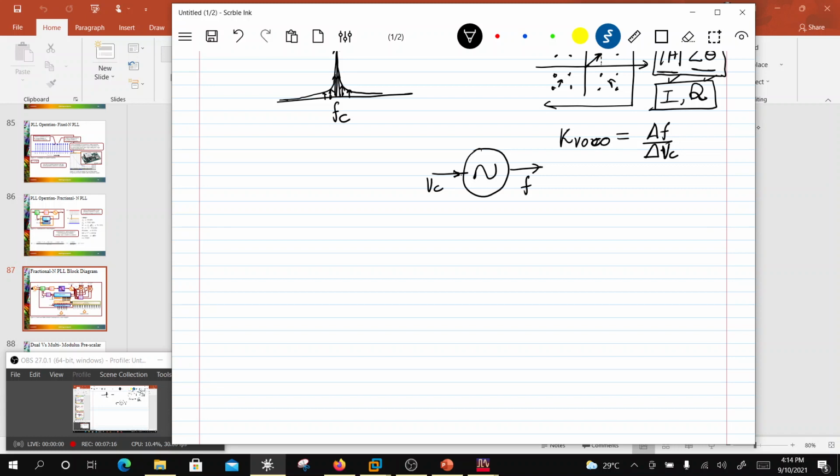Now the issue with this is the following. Let's assume a sine wave, and we are supposed to produce this pure sine wave, and then there are these zero crossings, right? Because of the noise, these zero crossings can slightly shift like this, and this can be a random process. They can take any value nearby this zero crossing. So this is a form of phase noise, and the idea is to stabilize this VCO so that we can minimize this phase noise.